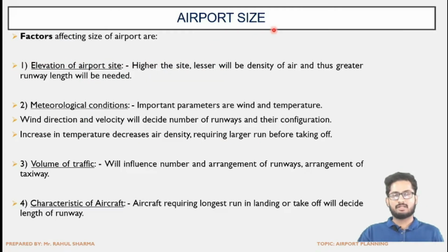Next topic is the airport size. Now, which are the factors ultimately affecting the size of the airport? First is the elevation of the airport site. The higher the site, the lesser the density of air, and thus a greater runway length will be needed, and the more the runway length, the more the airport size. This point we have studied in detail in the chapter on runway design as well.